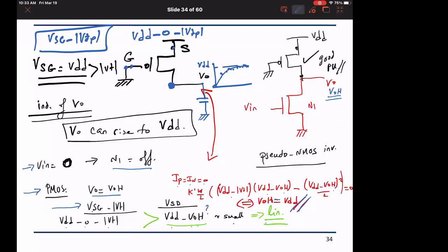What I was trying to explain above is that when I had the NMOS device, its VGS was VG minus VO, right? So it had a possibility of turning off if VO becomes very close to VG, versus in this one, VO will not turn it off when it gets within a delta of VT from VG, because this is what turns on the channel, regardless of linear or saturation.